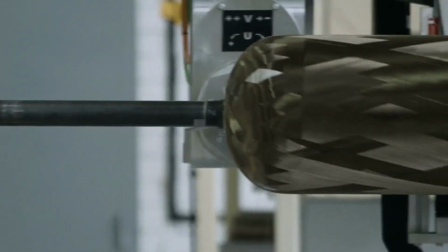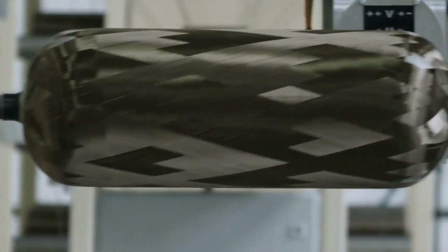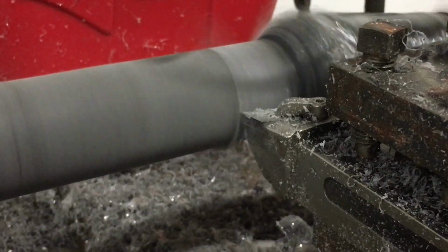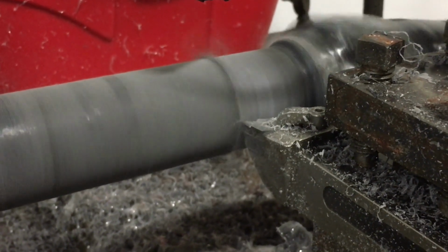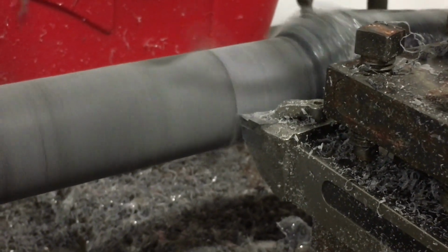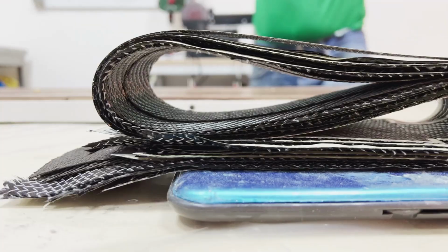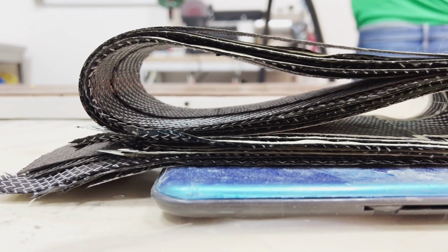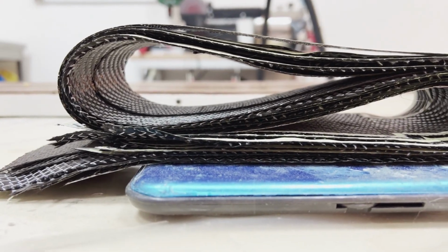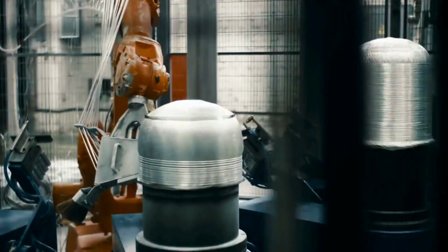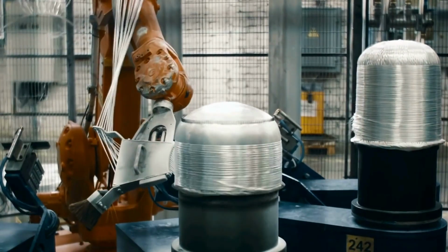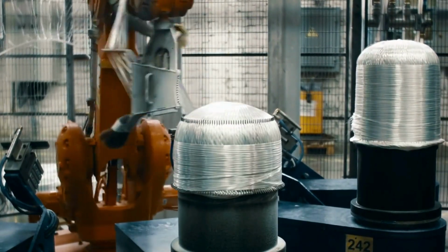It often appears as a black woven fabric or a bundle of very thin threads. In reality, its internal structure is extremely sophisticated, and its production process is one of the most technologically demanding in materials engineering. Each individual carbon fiber filament is made of millions of carbon atoms arranged in a highly ordered crystal structure. These atoms form long, layered chains that run along the length of the fiber. Because of this orientation, the fiber can withstand enormous tensile forces without breaking.